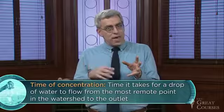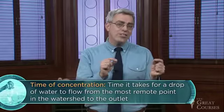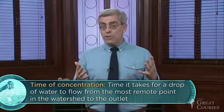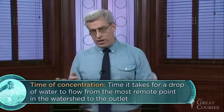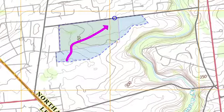contributing to the flow. To represent this condition mathematically, we'll calculate a parameter called the time of concentration, defined as the time it takes for a drop of water to flow from the most remote point in the watershed all the way down to the outlet. Once that drop of rainwater has flowed from this point overland along this path to the outlet, then we'll know that the entire watershed must be contributing to the flow because every other possible path to the outlet is shorter.